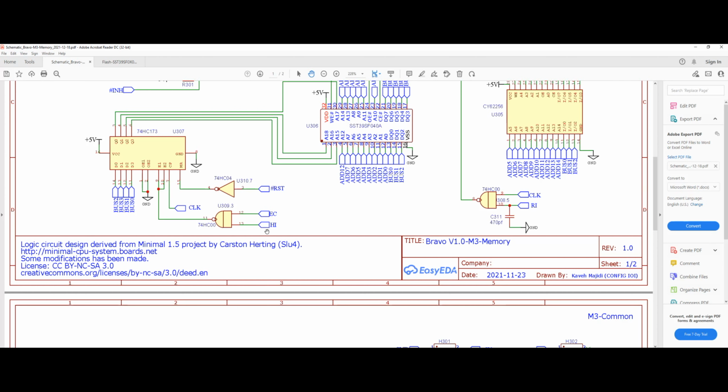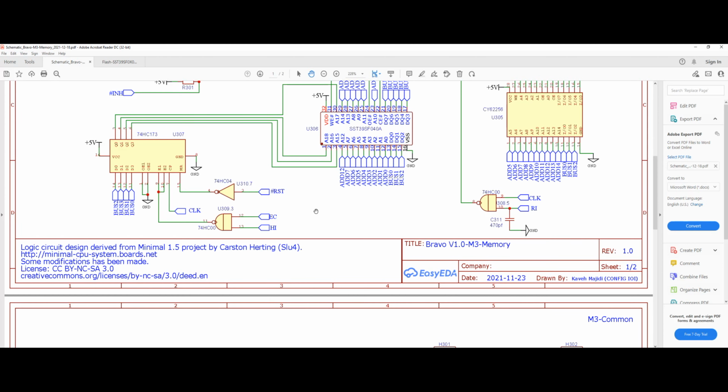And the HI signal was the signal that we were using to activate the high byte of a circuit, right? However, the beauty of this computer is that we are recycling a lot of signals, and we are using different signals by combining them together to come up with a unique signal. That means that we are not outputting a specific dedicated signal just to control our bank.